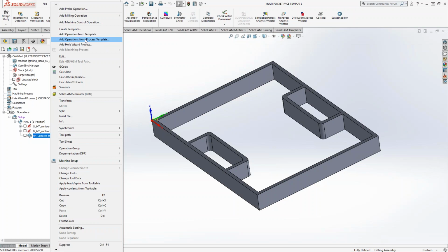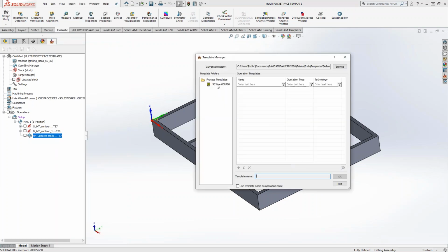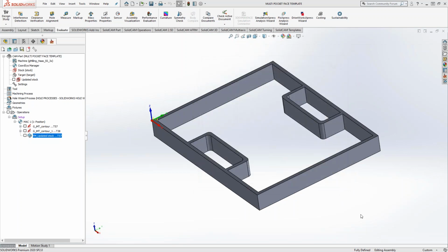It adds all those tools. So let's say, for instance, if I open this up and take a look at one of these toolpaths that we did before, these templates, there are 4 operations there. There are 4 sets of tools in there. So if I were to load this template, all 4 tools would be added to my tool table, or all 4 toolpaths will be added to my toolpath list, and then each one would require me to choose the new geometry. Or if they share geometry, then I could choose one set of geometry and assign it to all of them. Basically, when I do that, it's going to ask me what the geometry is, what the levels are. We're going to go through that today in a more practical example. But basically, template versus process template is either a single operation or a group of operations.